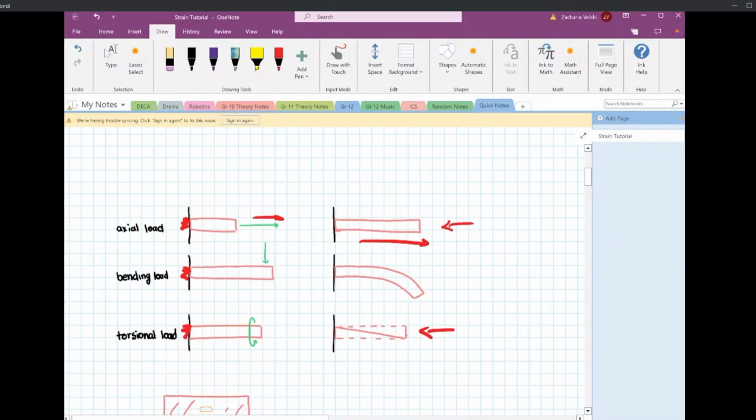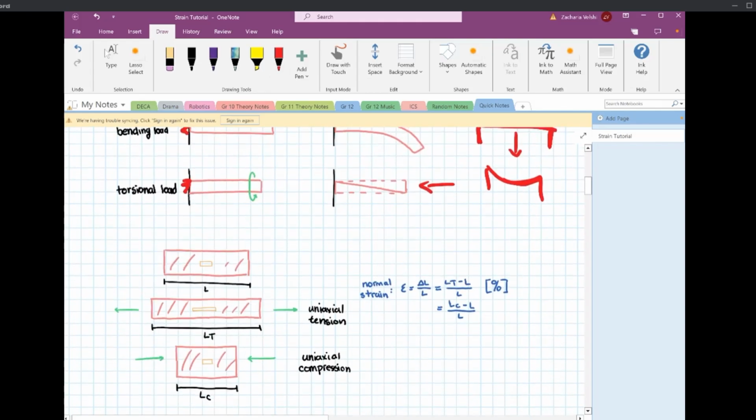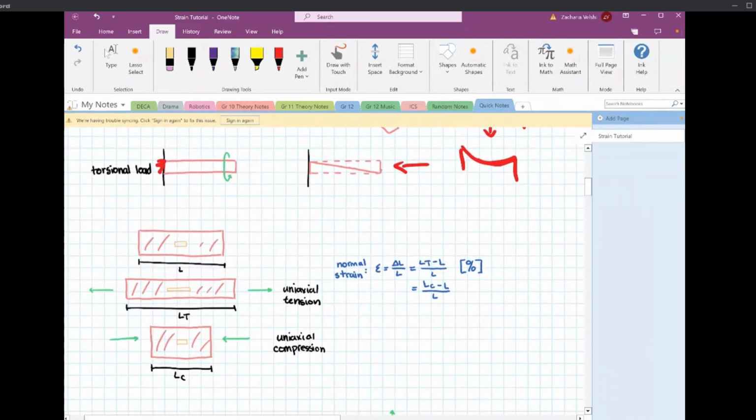Bending we see on the engine runners. You have your big engine that's a mass, and it sits on here, and it's pinned on these two sides. The engine mass hangs down right in the middle, applies a load right in the middle, and this will tend to deform just like that. And we can get the force that goes through this member as well, which is bending.